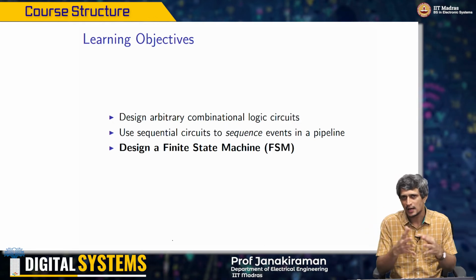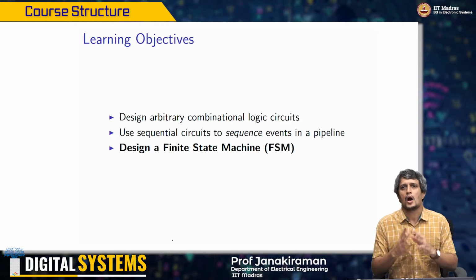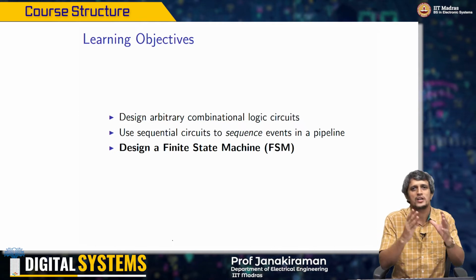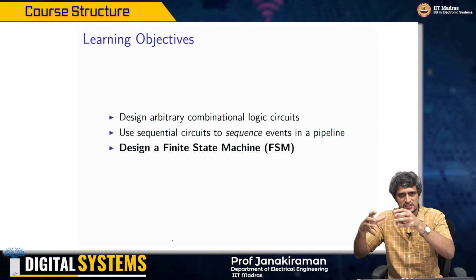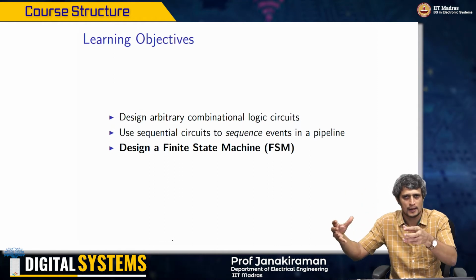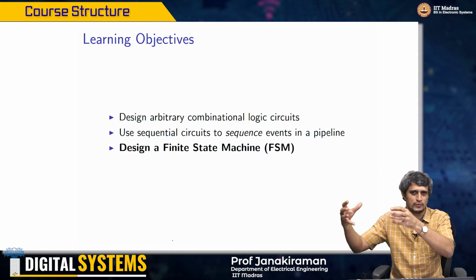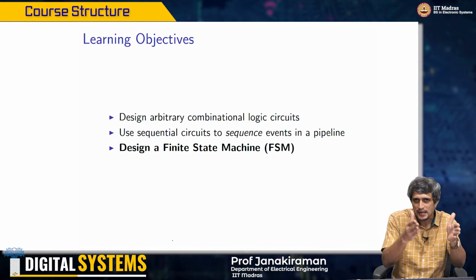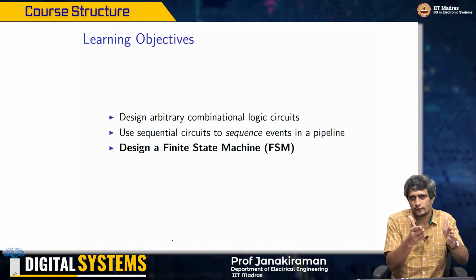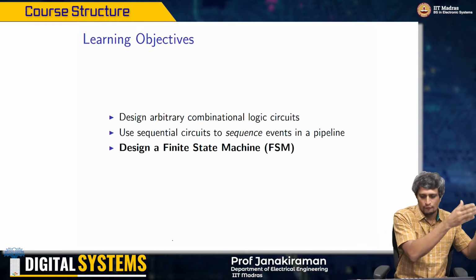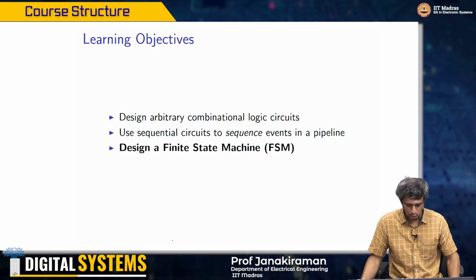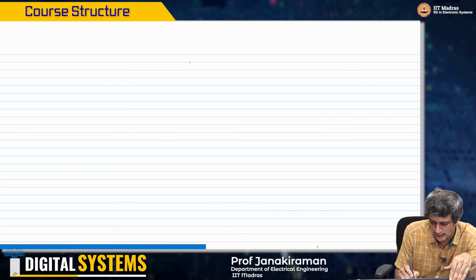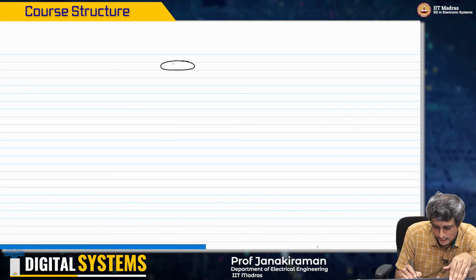So what is this counter doing? The counter is actually going from one state to another. What is the state? It is going from state 59, which represents the number 59 on seconds. After 1 second, it goes to state 58, 57, 56. So if I were to just look at the state machine of your traffic signal counter, it's like this.